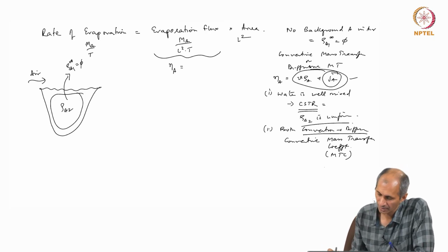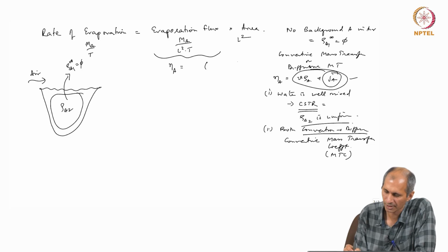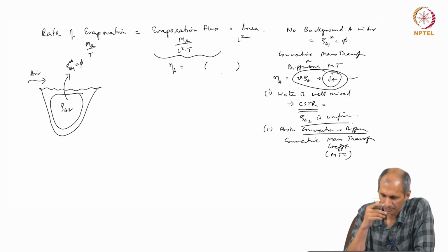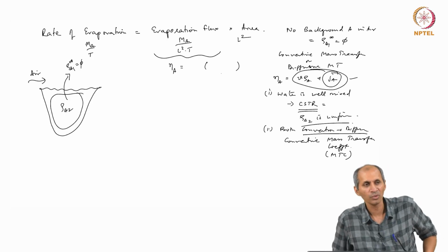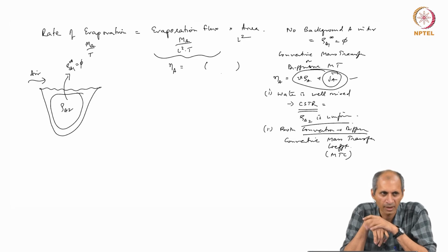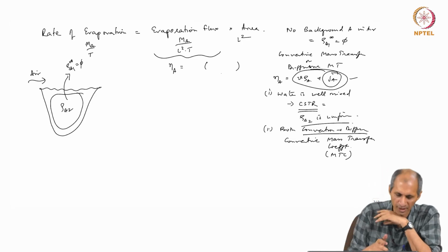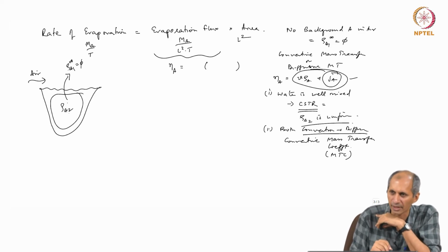Okay. Now, we have decided that, so which means there is a K mass transfer coefficient term multiplied by a driving force that needs to come here. So, we will start with the driving force. So, yesterday's last class we had discussed how we can write this flux term, and we have various options for doing it. So, in this particular scenario we are taking rho A2, which is a solution in the aqueous phase going into the vapor phase in the air.